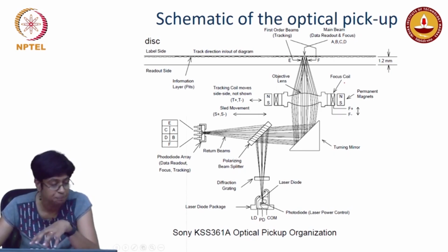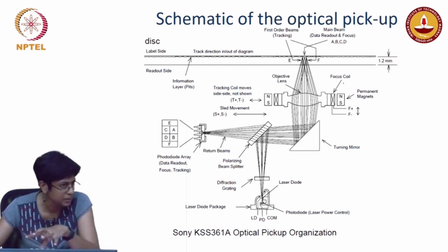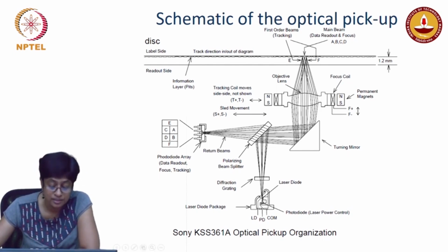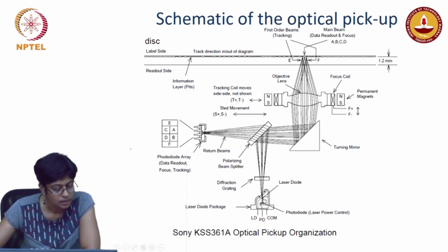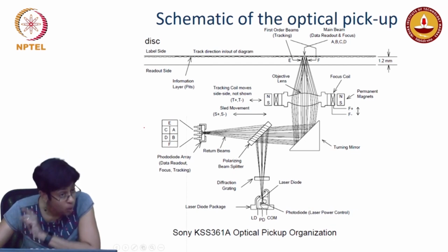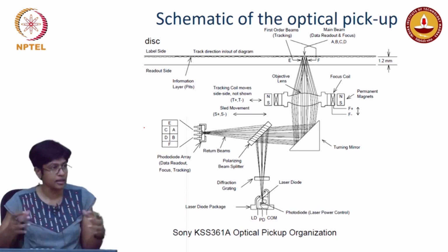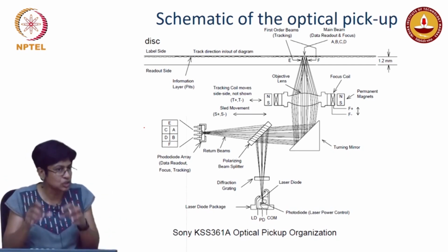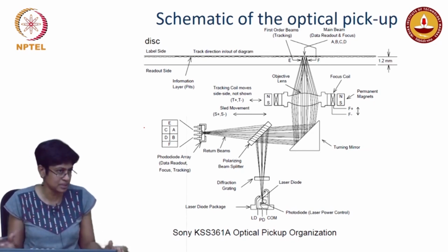Here there must be something on the way. You can have a polarization change in reflection, so they may be exploiting that, so that the returning light is of a different polarization and therefore will pass through the beam splitter and not get reflected. Then it goes to this photodiode, but it's not one photodiode anymore. It is an array containing 6 individual units. It's all together, but you could read them separately.